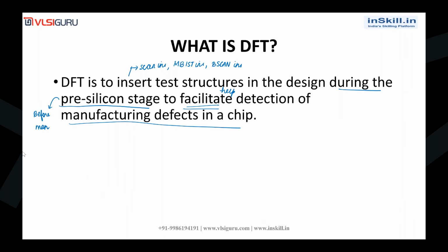We will be adding our own test structures in the design, like scan insertion, MBIST insertion, boundary scan insertion, during the pre-silicon stage. Pre-silicon stage means before manufacturing, to help detection of manufacturing defects in the chip.